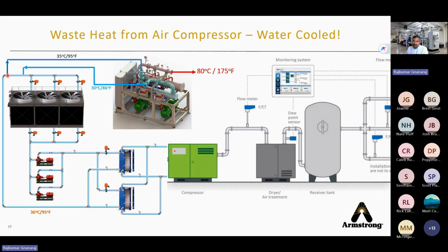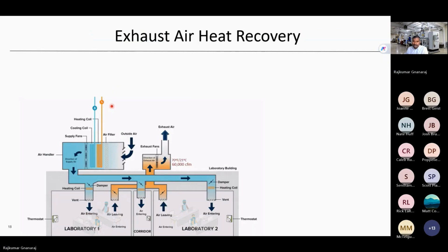So take the cooling tower return water, the way we saw with the chiller, use that in the heat pump evaporator as a waste heat source, and generate 175-degree high temperature hot water. So in a facility where there is only a cooling tower, you can still use the cooling tower water as a source in a heat pump to generate higher temperature hot water.